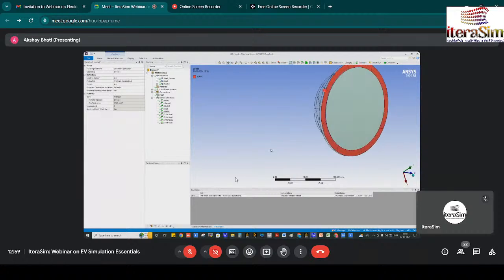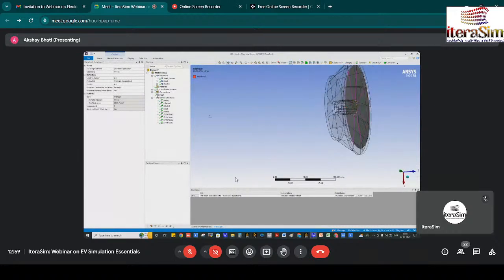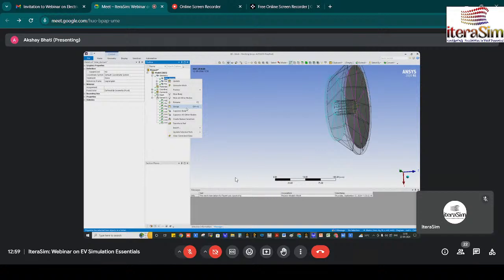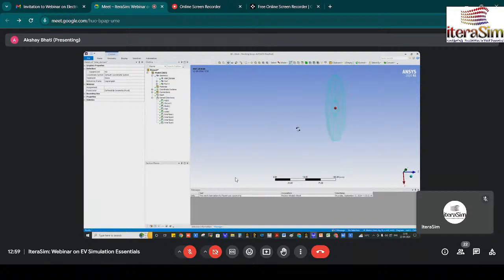That's why I provide a solid support over there, so that I can give the flow of the air to that casing part only. Because I have deleted the contact zone, first I need to connect the three bodies. If we talk about the inlet domain, hide all other bodies. Here use the inlet body and interface one.